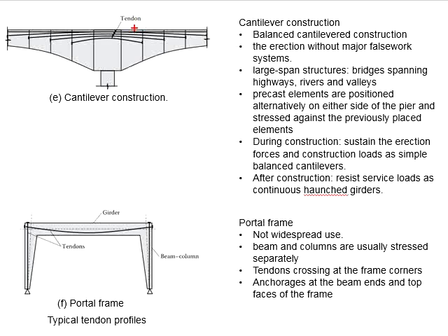Or we can install the segments alternately beside the piers in order to minimize the effective moment caused by the eccentricity of the center of gravity of the bridge relative to the central axis of the pier. This will minimize the turning moments acting on the pier during the construction.